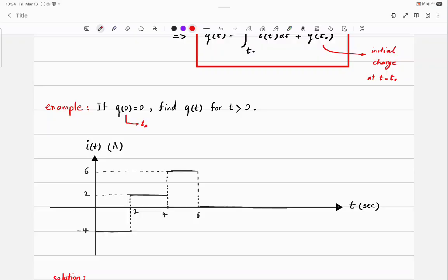Because it goes from positive to negative instead of negative to positive, so you have to subtract it. So what is the meaning of that 2 volts across element A with that positive and negative sign? It means that the left terminal should be 2 volts higher than the right terminal. The left terminal is 4 volts, so the right terminal must be 2 volts.